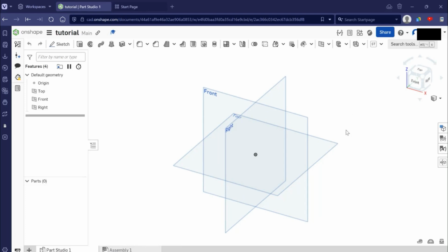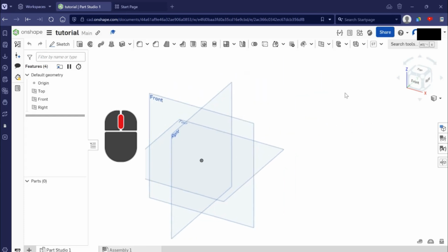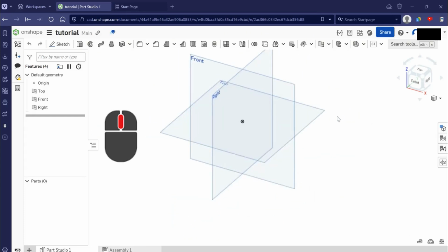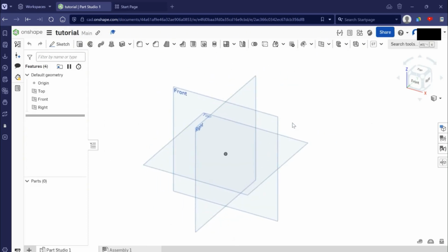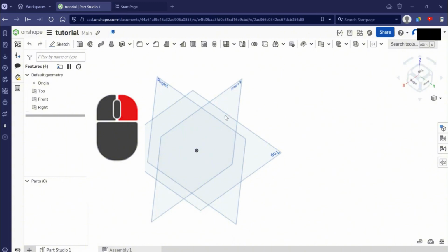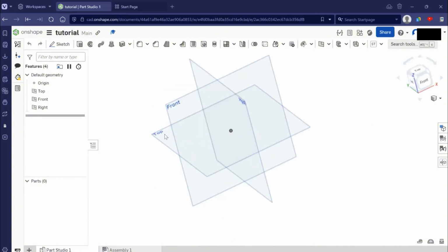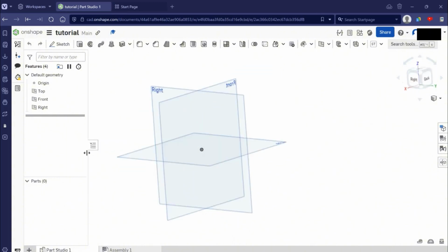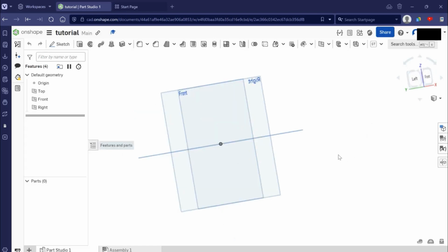So over here, to actually move around the interface, you use the middle mouse button to pan around where we are, all right? This is called panning. And hold the right click and then drag to turn or rotate the viewpoint, all right?